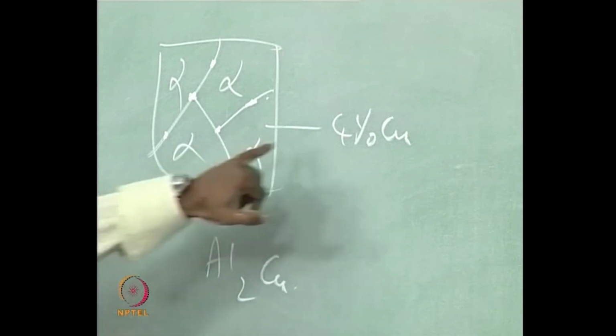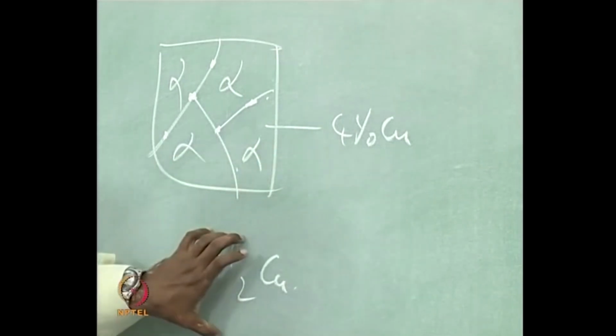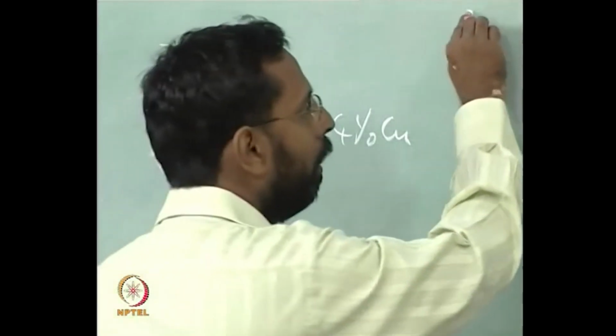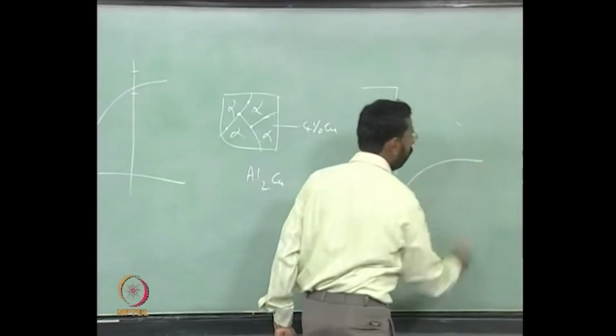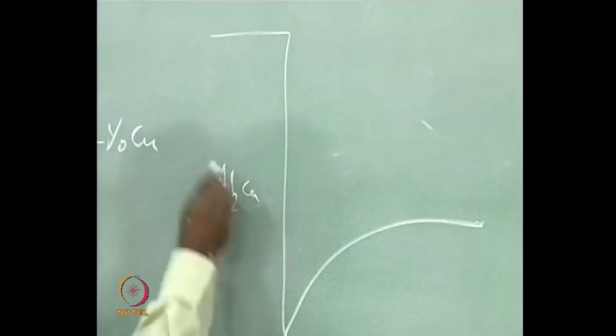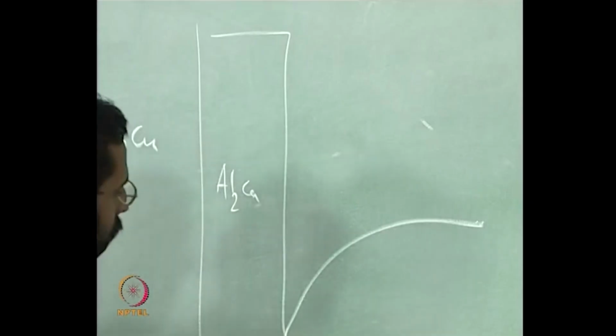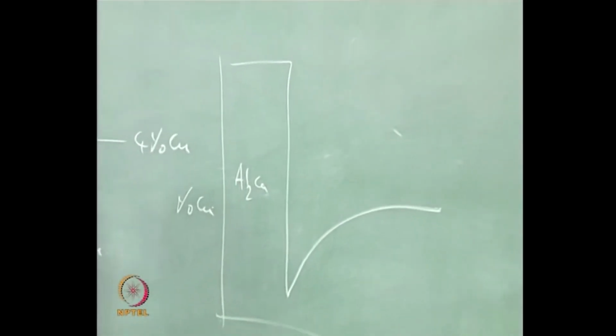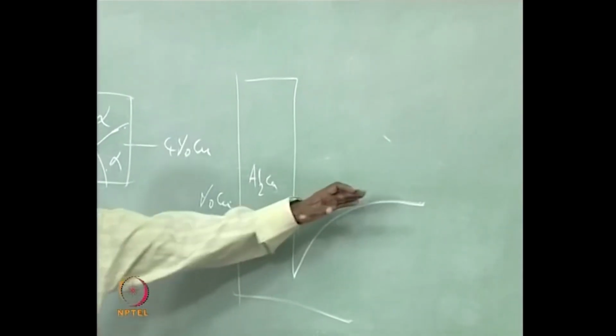So, if I am considering such an alloy, then if this has to nucleate and grow, you need copper atoms to come from the matrix to this precipitate, and you have seen this happening when we talked about this. If this is the theta phase Al2Cu, if we plot percentage copper, what is called the concentration profile looks like this.